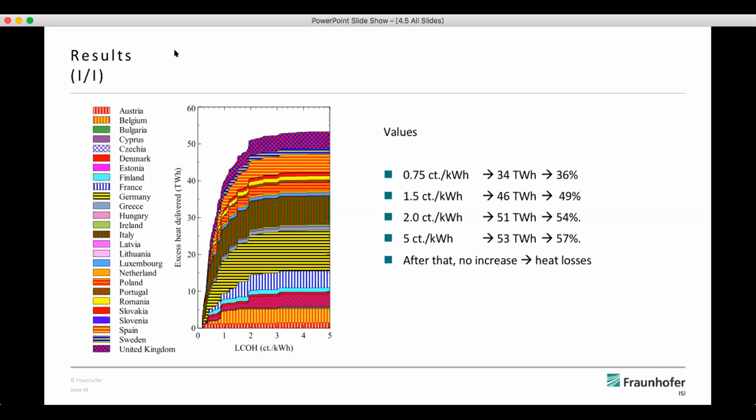But we also have heat losses foreseen in the pipe dimension, and we don't optimize the pipe dimension, so we are not increasing the sizes. We are only using standard values from engineering tables. So if the heat losses are too high, in the way that we lose too much heat, we are also cutting these pipes.